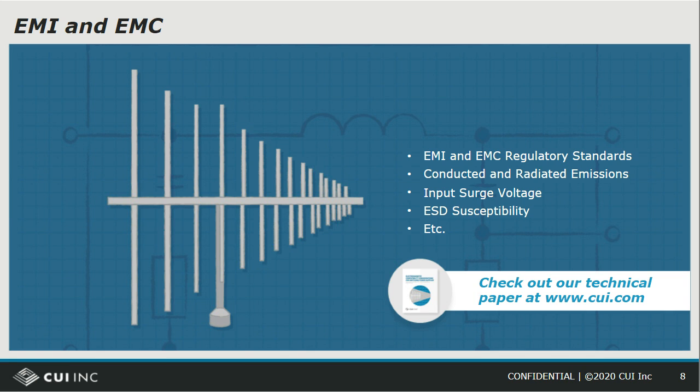And at that point, the power supply is present and the radiated and conducted emissions are oftentimes detected near the power supply. So therefore, it is viewed as potentially the source of it and the place where the solution should be found, but it is not necessarily actually the source of the problem.